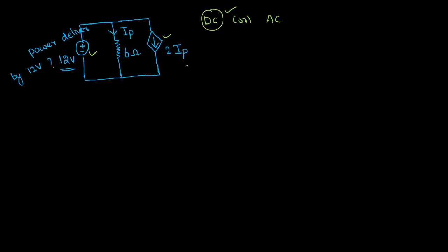First conclusion. When it is a DC circuit, immediately tell me the formula to calculate the power. In a DC circuit, the imaginary power is completely zero. We have only real power. The real power formula is VI cos phi. But when the circuit is purely DC, the phase angle difference between voltage and current is always equal to 0, so the value of cos 0 will become 1. So the formula to obtain the real power is simply voltage into current only.